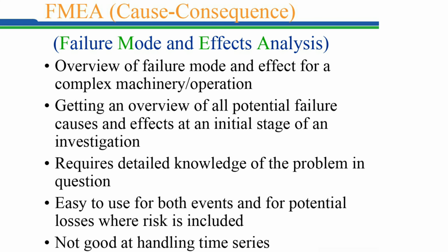FMEA, cause-consequence, failure mode and effects analysis. Overview of failure mode and effect for a complex machinery and operation, getting an overview of all potential failure causes and effects at an initial stage of an investigation. Requires detailed knowledge of the problem in question, easy to use for both events and for potential losses where risk is included, not good at handling time series.